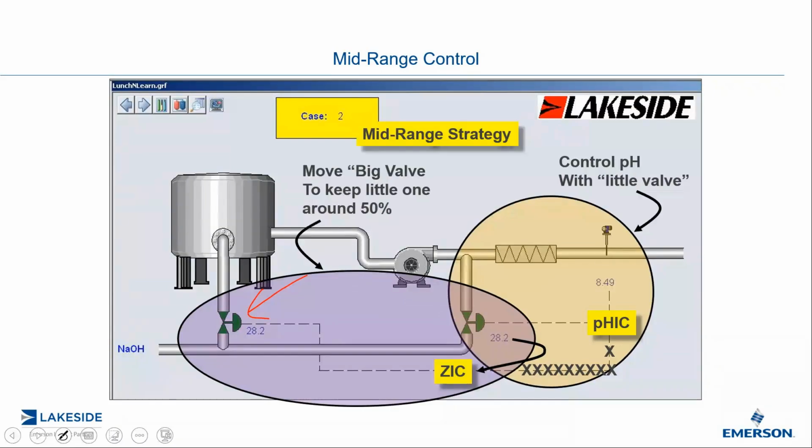And let's say it has a cycle of 10 seconds. So that means that at 100% that valve is open for the full 10 seconds. If the output is 50%, that means the valve will be open 5 seconds and closed 5 seconds. If the output is at 10%, that valve, big brother, will be open for 1 second and closed for 9 seconds. So the answer is yes.